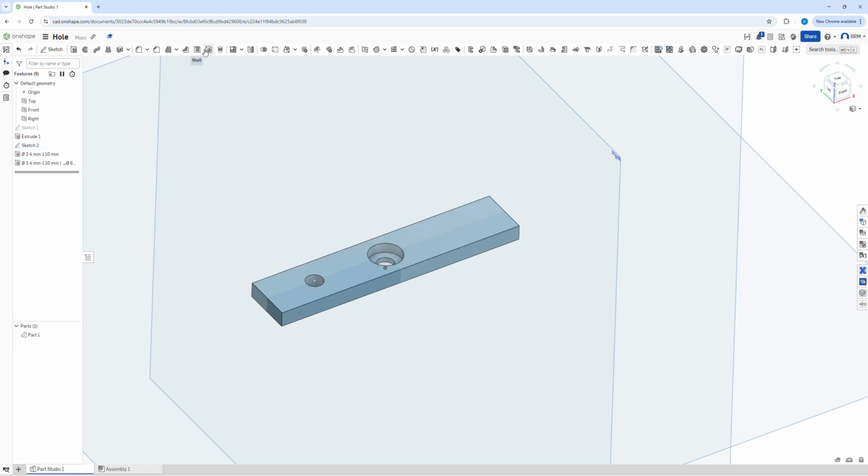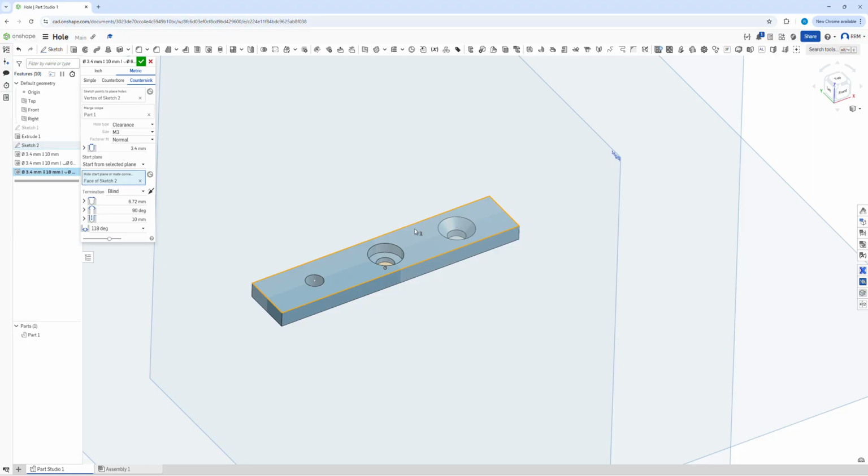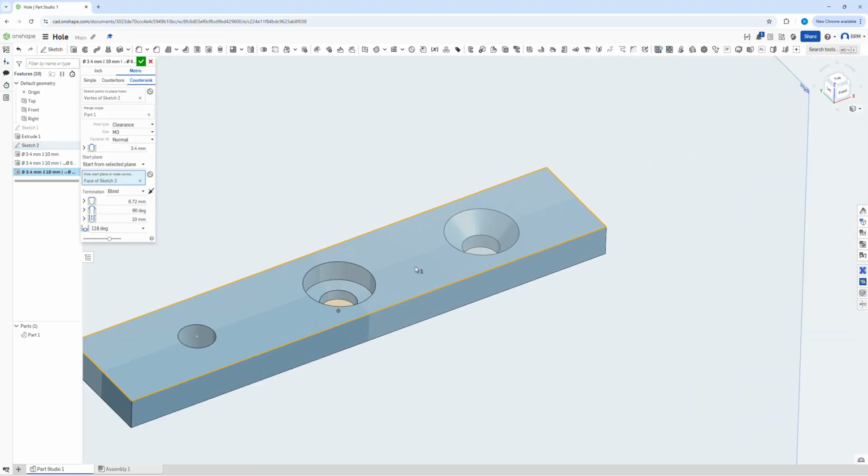And then finally, we've got our countersink hole. Okay, so exactly the same thing, the position, select a place where we want the countersink to go. It's going to be there. Clearance is fine. Again, we can play with those depending on what you're doing. Start hole position is going to be this plane like so. And what you'll notice, this has an angle. Okay, so a wood screw will have a countersunk shape that's kind of at an angle.